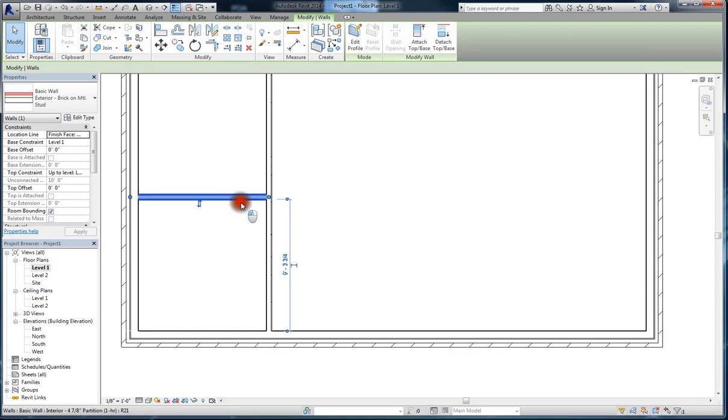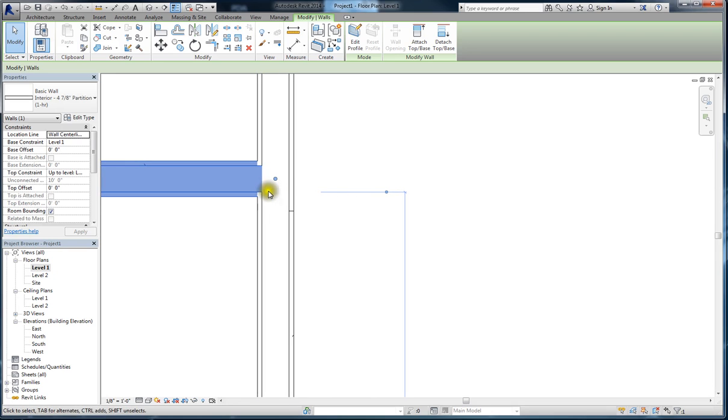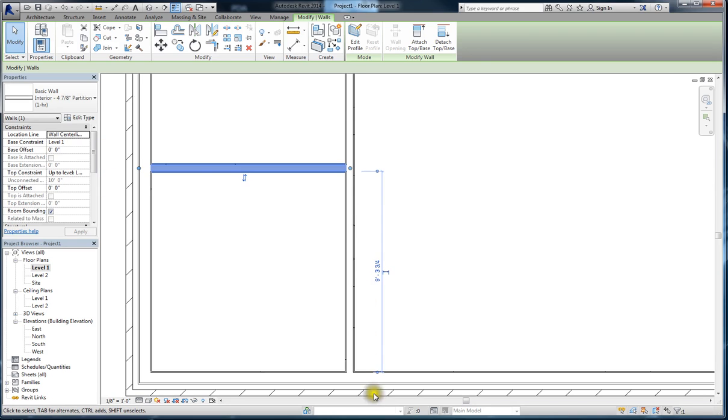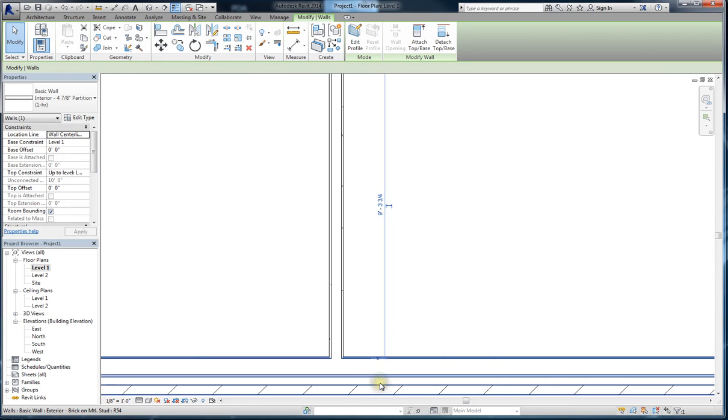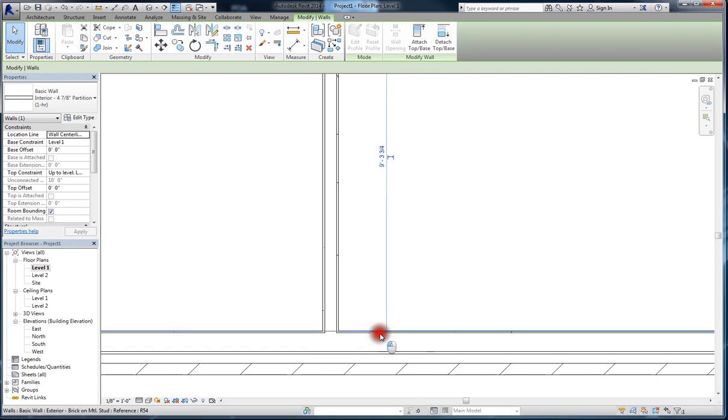So now, here we go. When I select a wall, any wall, the temporary dimension is lining up with the core face, which in this case is the stud face. Up there and over here as well. Now remember, these temporary dimensions have these little blue bubbles that I call. If you click on it one time, it jumps to the next face. Click on it again, center, or there.